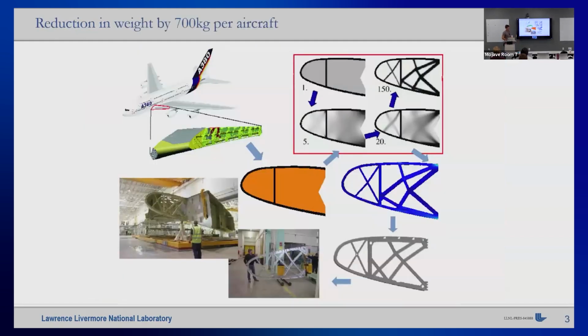And at the time, and even nowadays, the most common topology optimization tool was this density-based topology optimization tool. So in this tool, basically, we have these densities. A density close to 0 means that's a void region, and that's normally white in here, and that beige and black, which is black, is material. And so we normally start with an intermediate design density field, and then throughout the optimization process converge towards a black and white design, and that's then our final structure.